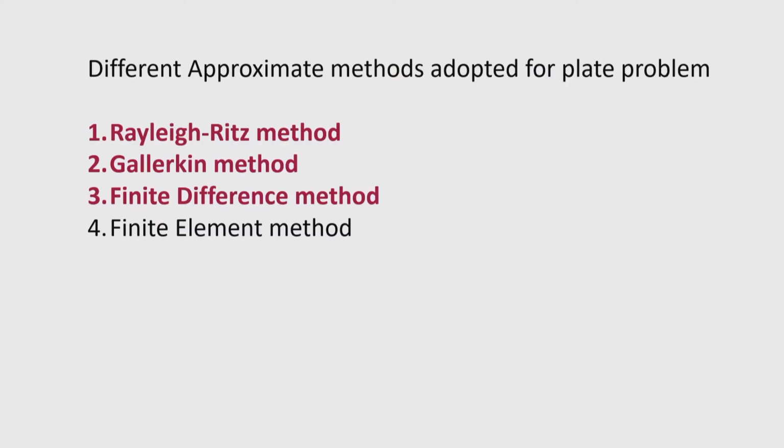The other two methods that I have listed here, one is Rayleigh method and another is Galerkin method. These also, in the final step of formulation, you will get that the equations to be solved for unknown parameters are all linear simultaneous equations. So, in all the cases we require to solve only linear simultaneous equations for the plate problem. So, therefore, it becomes easier for the analyst to use this method for such problems which could not be handled by exact solution approach.